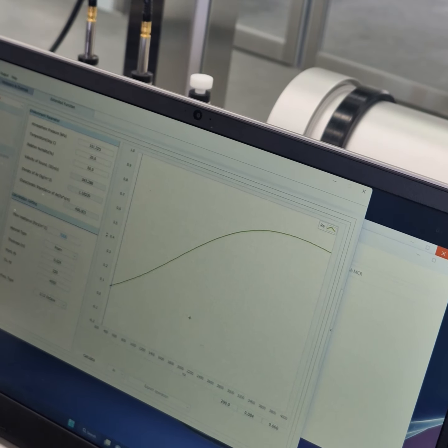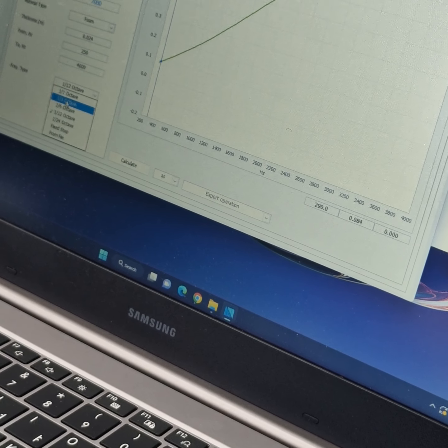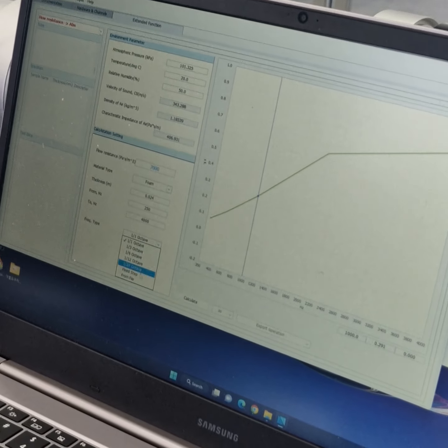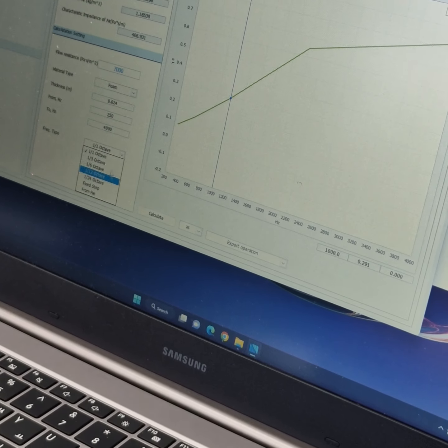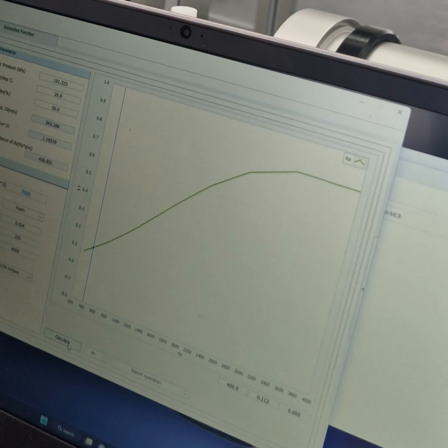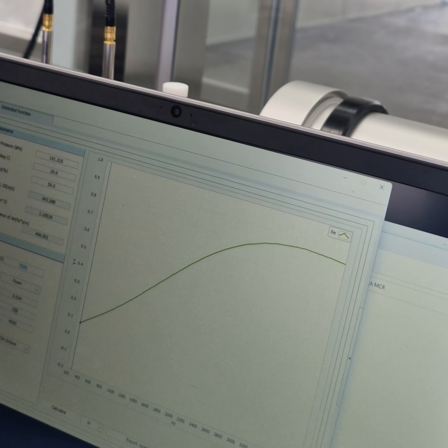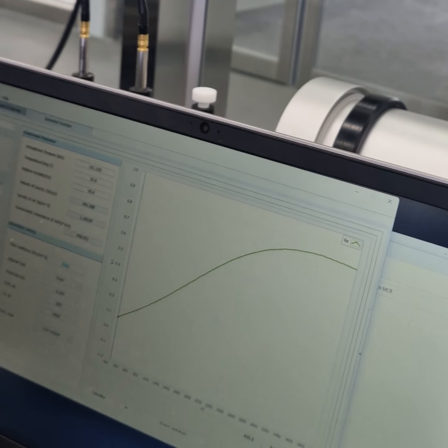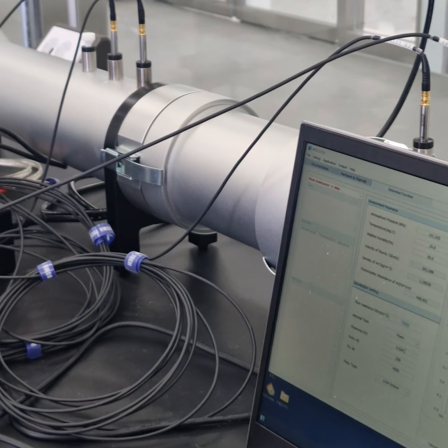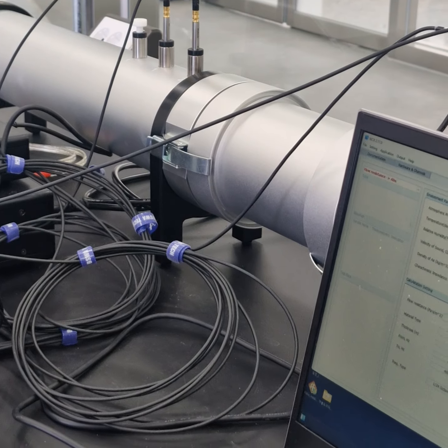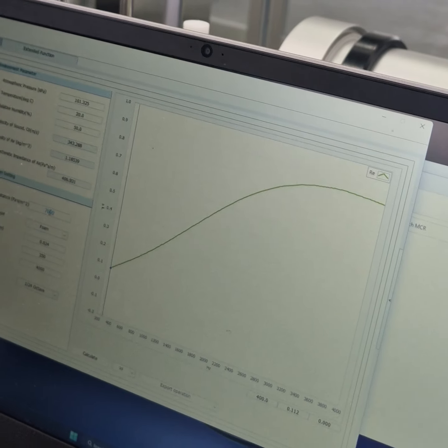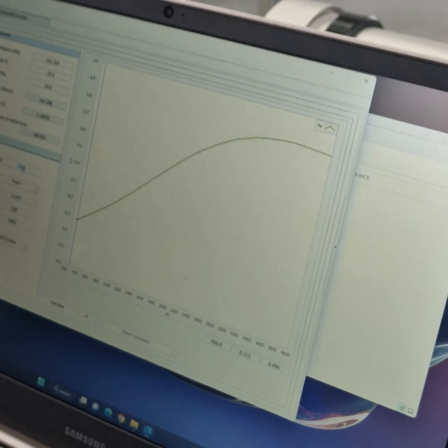You can also select the frequency type, 1 octave band, and if you want it to be more accurate, you can pick whatever you want, and also select the frequency step and the frequency range. The two main things that determine the absorption of this material are the flow resistance and the thickness of the material. You need to set up these two, then everything should be calculated.